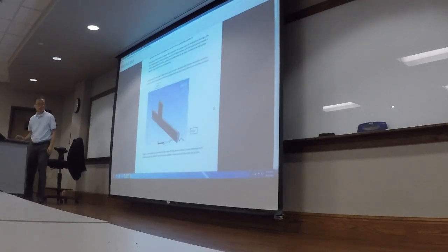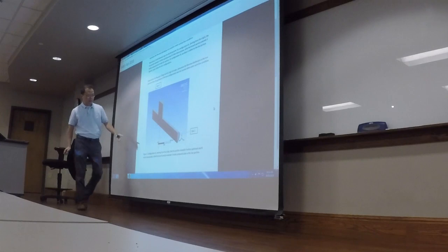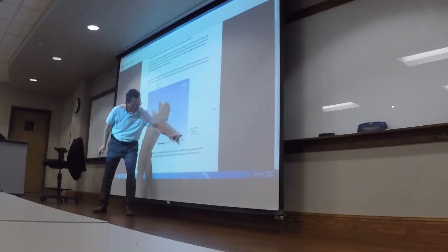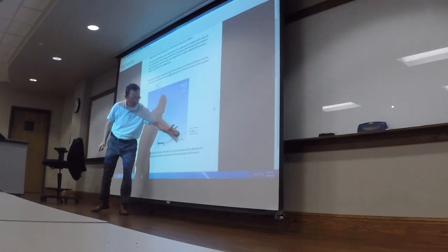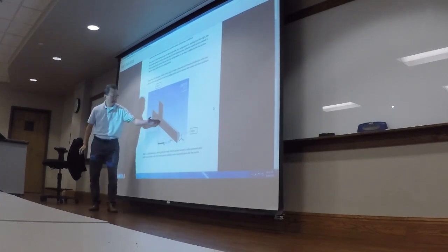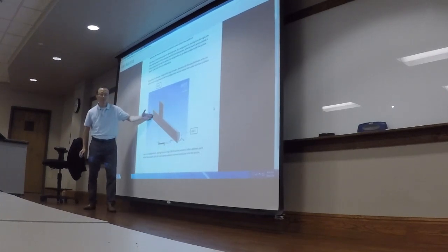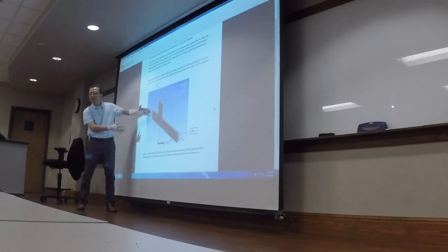I want to show you how to set up this flow. All right, so let's see. This is X, Y, Z. What we're going to do is start from the YZ plane. Let's create a new plane, 4 inches in the negative X direction.